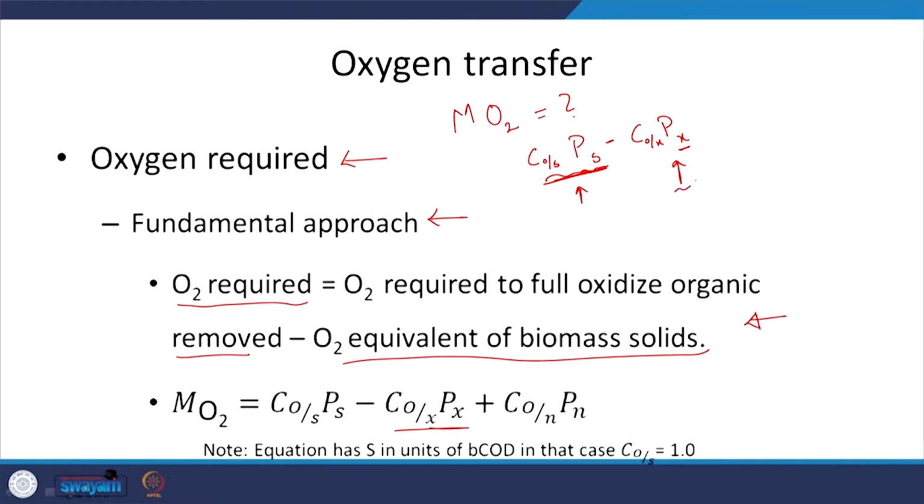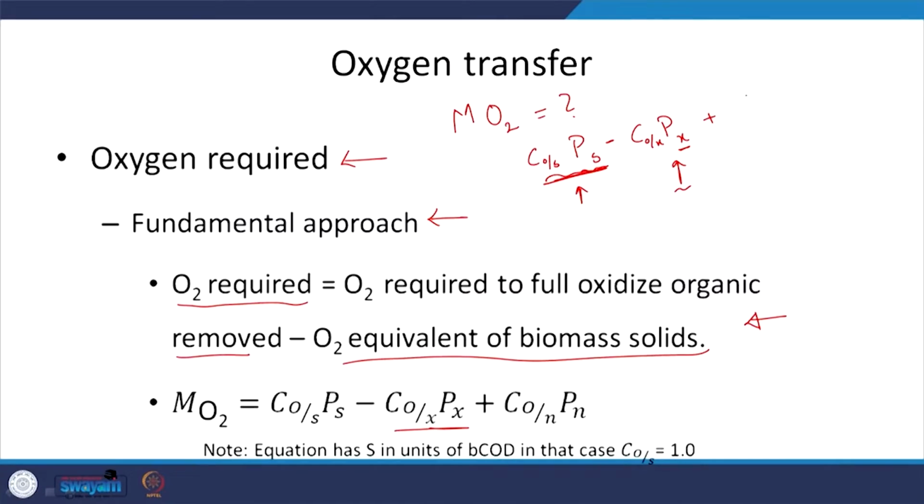And if I need to look at nitrification, as in if I have ammonia, NH4+ or NH3 let us say, and I need to oxidize it, right. We looked at ammonia oxidizing bacteria and nitrite oxidizing bacteria in this context. Again, how do they oxidize? With the assistance of oxygen obviously, right. So, you need the oxygen. So, whenever you have a requirement of also removing nitrogen, we have this particular term, right. That is a better way of understanding the relevant concept here.